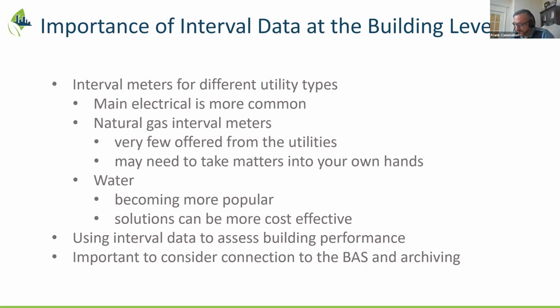Question for you. When installing a main natural gas meter or natural gas sub meters, what you want to do first is understand what your application is. In some instances, for some municipalities, we're doing billing applications where they're metering tenants in their space. If that's the case, it needs to be a Measurement Canada approved meter, because Measurement Canada regulates natural gas in Canada. So you're limited to an inline diaphragm or rotary meter that needs to be sealed and commissioned in the field.